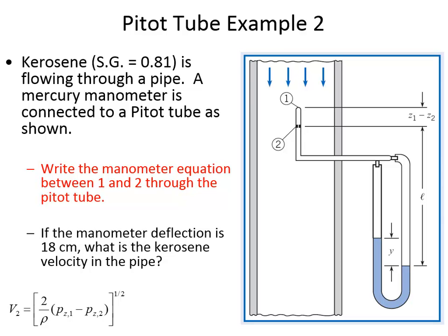Sometimes they'll use a really expensive and sophisticated magnetic ring that goes around the pipe, and they actually measure the mass flow rate of the fluid that's going past magnetically. Other cases they'll use a physical measurement like this to try and find out what's the velocity and then multiplying that by the cross-sectional area.